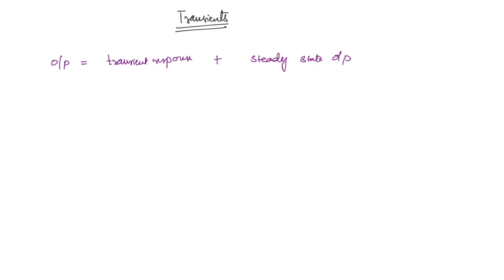This is easily understood if you take a measuring instrument. If you take an ammeter, let us say, as soon as you switch on the supply after you have given all the connections, what will happen to the pointer? Here there are readings, let us say. Now the pointer, initially it was at 0. As soon as you switch on the supply, let us say 2 amperes is the current it is going to measure. Then it will swing on beyond 2 amperes and then swing back and forth at 2 amperes and then finally it will settle down at 2 amperes.